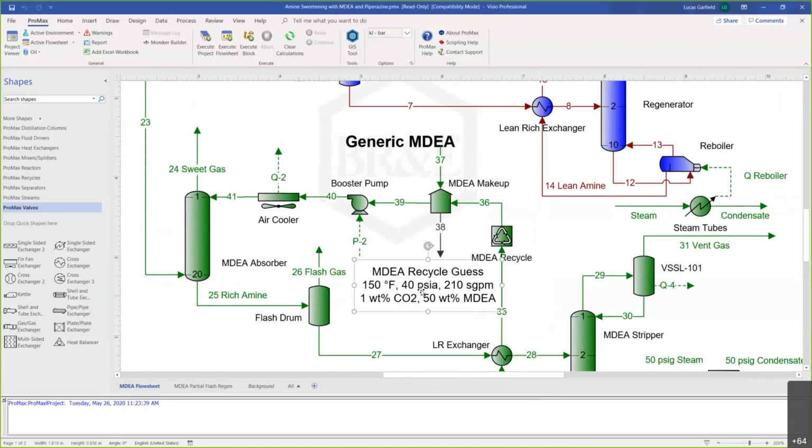I've got a question from Manikandan asking about simulating CO2 capture processes. There's a question, does the licensor solvent hold any additional proprietary data that prevents us from fine-tuning the simulation? I would say generally no. If you have the correct MDEA and piperazine content in your simulation, you should be able to match what the